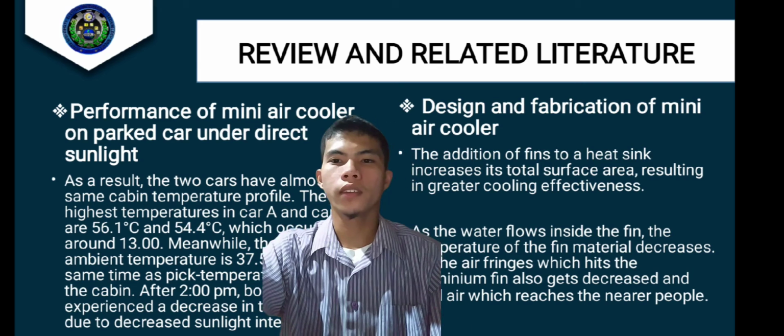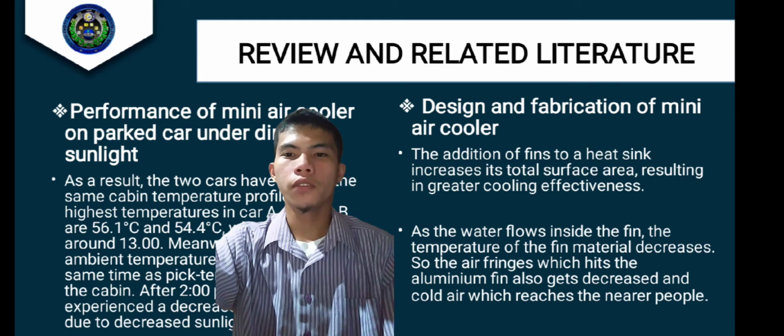The second one is the design and fabrication of a mini air cooler. The addition of fins to a heat sink increases its total surface area, resulting in greater cooling effectiveness. As the water flows inside the fin, the temperature of the fin material decreases, so the air which hits the aluminum fin also gets cooler, and cold air reaches the people nearby. The design of cooling fins is encountered in many situations, and we examine heat transfer in a fin as a way of defining some criteria for design.